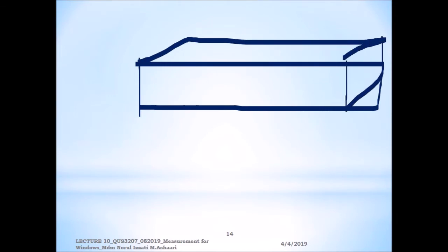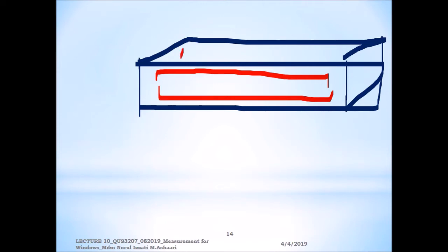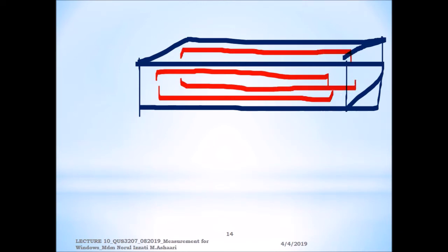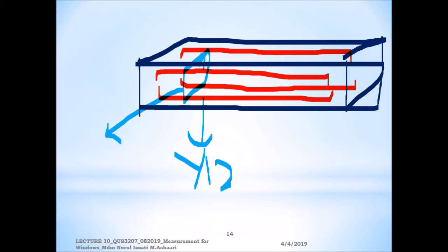Okay, let's say the bar reinforcement, you have 2 on the top, 2 at the bottom. Then this one must be clearly stated in the description. Say you have another one that is stirrup. Okay, so maybe for the red color, this is Y12. Depends on the detail. For this blue color, maybe this is R6.